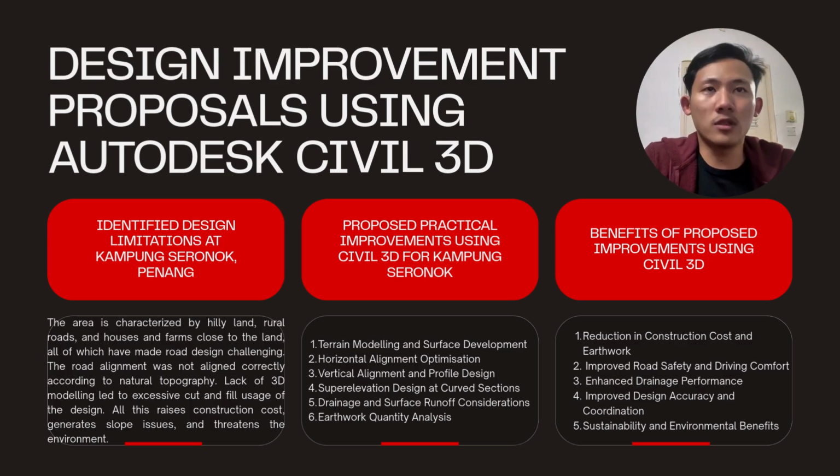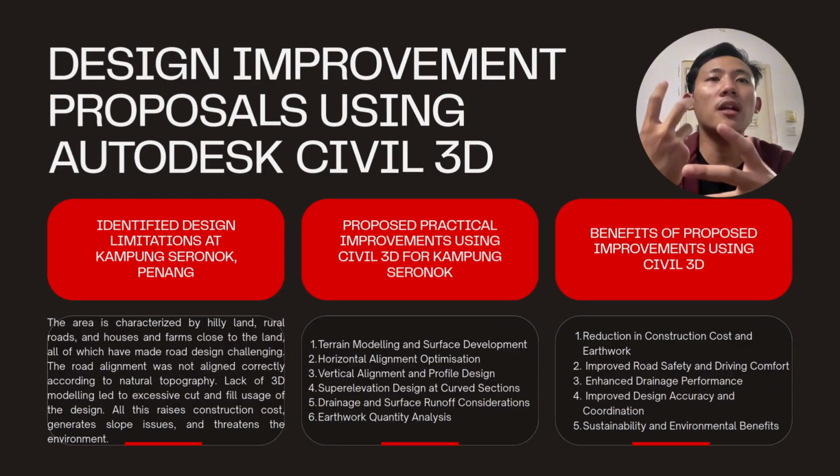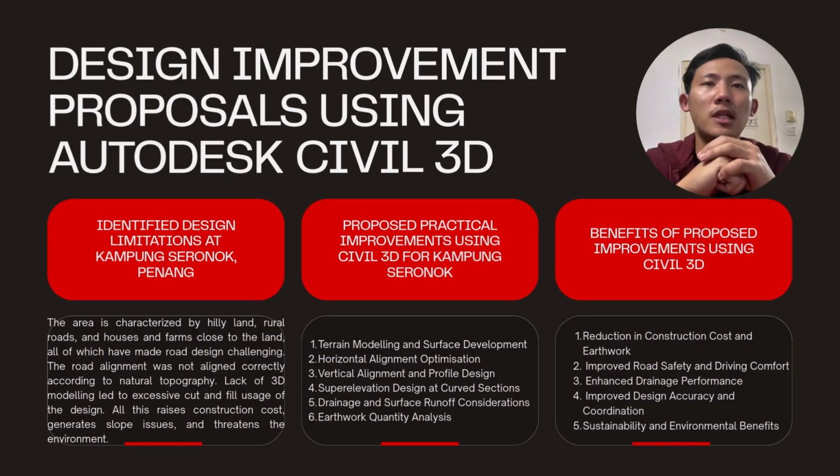To address this problem, Autodesk Civil 3D was used as the main design tool. First, a 3D digital terrain model was developed to accurately represent the existing ground condition. This allowed a better understanding of the actual site compared to traditional 2D drawing. Next, the horizontal alignment was optimized to follow the natural curvature of the land, reducing sharp bends and improving vehicle maneuverability.